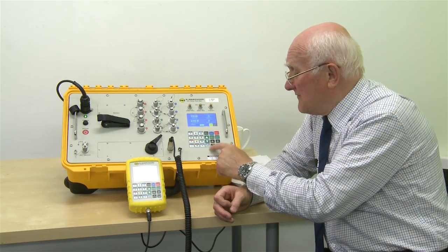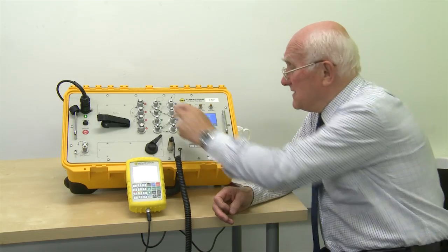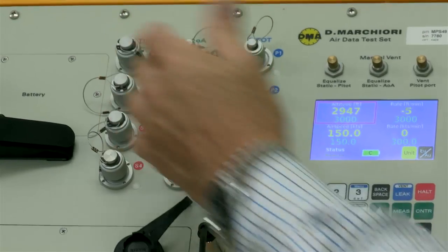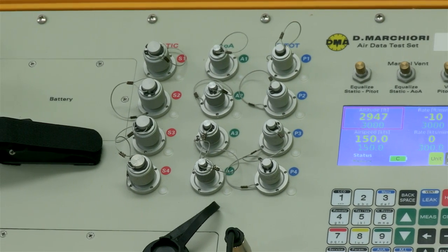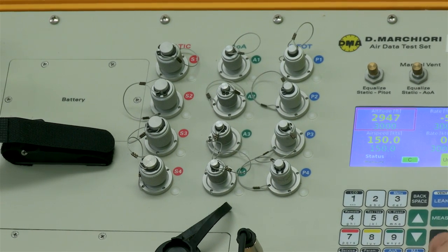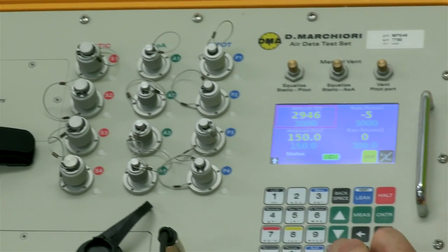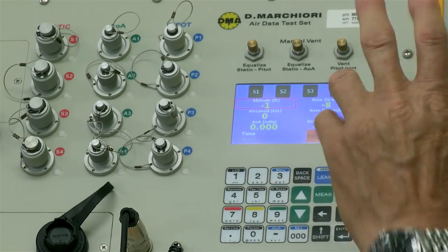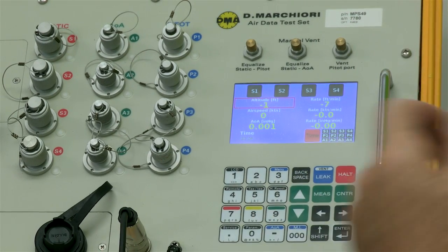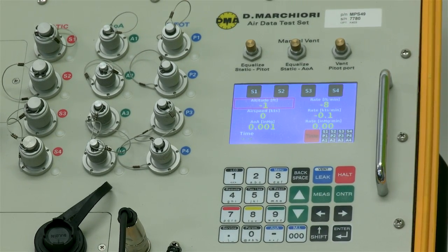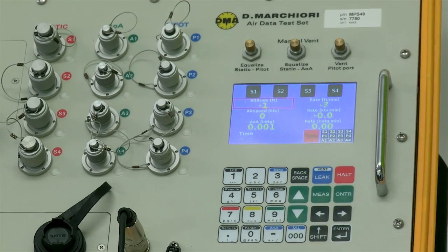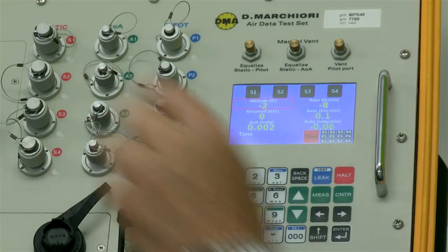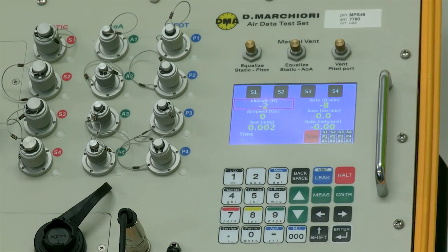And to do that, we have the multiple isolator, and that's what these are. We have the ability to isolate any one of those to find out which is leaking. To do that, we go to the Shift key and the multiple isolator. And that screen then shows us, just as it did in the other full measurement mode of the leak, the ability to select each one of these and switch it off, close it.